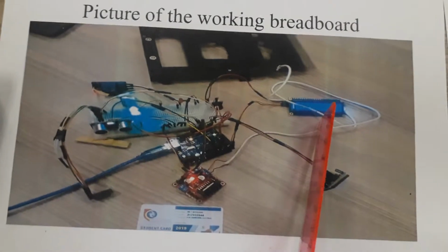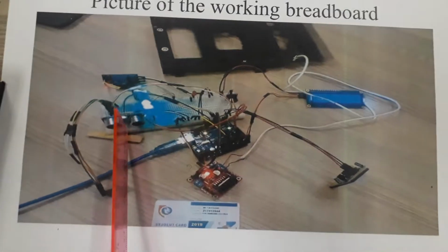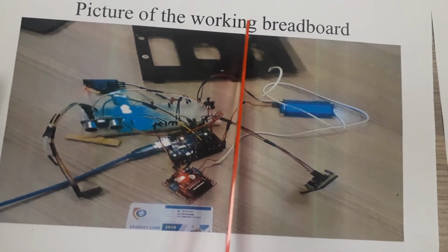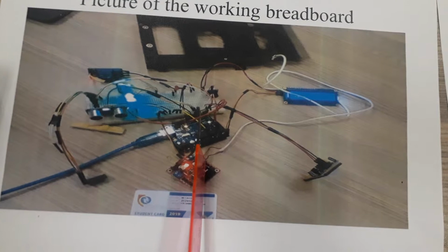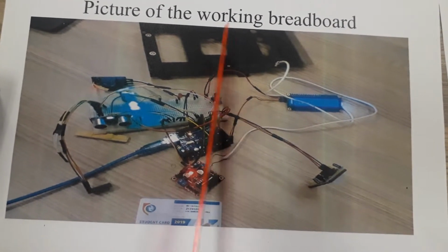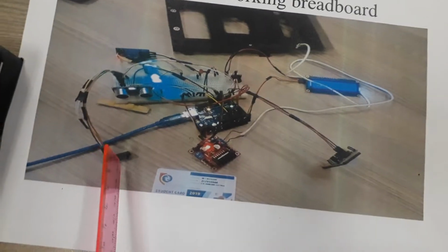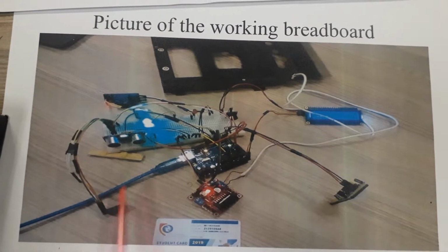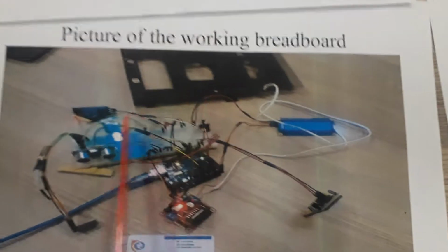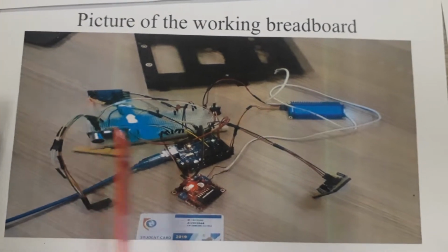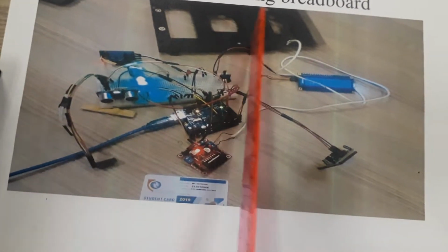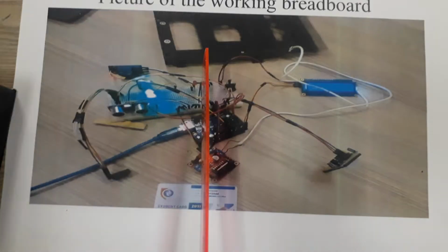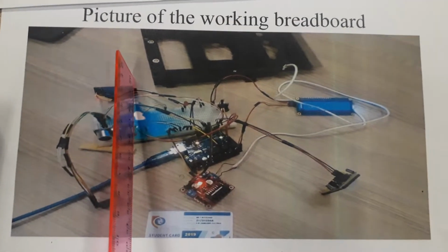And then the LCD will display the status of the door, the distance measured by the ultrasonic sensor, and the number of people going through the door. The motor driver will be the one responsible for opening and closing the door. And then the ESP8266 Wi-Fi module will send the data of my project to ThingSpeak. That data is the status of the door, the distance measured by the ultrasonic sensor, and the number of people going through the door. And for setting up the environment, I have the red LED that will turn on for 5 seconds, and it is controlled by the 5-volt relay.